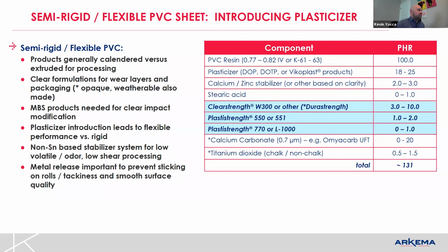The plants that I've been in who are really successful with QCing when things start to go wrong, they measure the bulk density of their silos and the blends going into their silos and keep a library. And it just lets them know when things start to shift, if something's off. Maybe they were pushing the blending order too hard and it led to a difference, because they do use some kind of control to feed the twin screws, and you start to see a thinner part. Maybe things aren't foaming correctly on a foam line. Maybe the gauge on the wall thickness for certain profile parts that are sensitive starts to go out of whack.